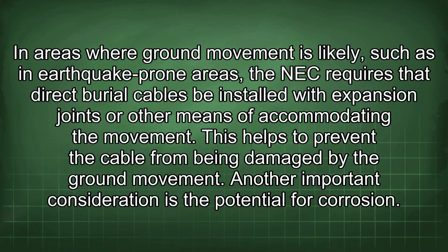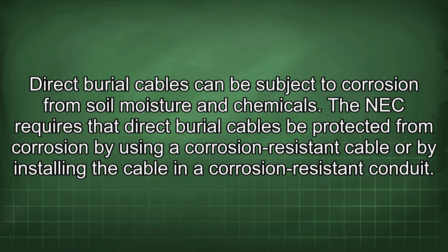Another important consideration is the potential for corrosion. Direct burial cables can be subject to corrosion from soil moisture and chemicals. The NEC requires that direct burial cables be protected from corrosion by using a corrosion-resistant cable or by installing the cable in a corrosion-resistant conduit.